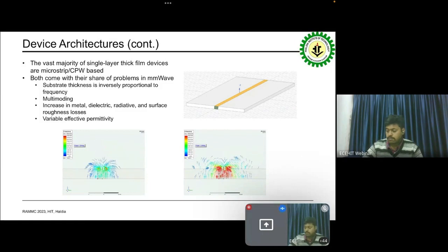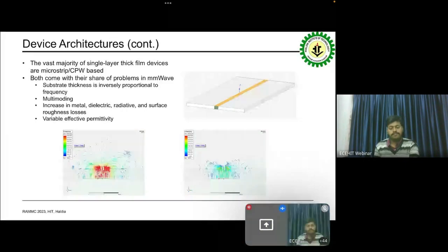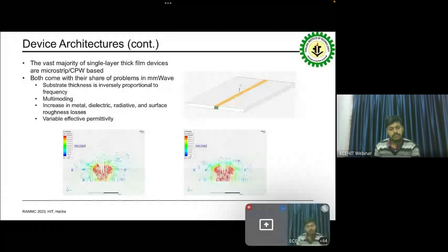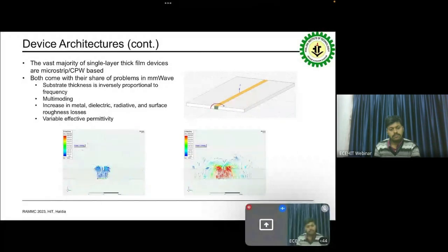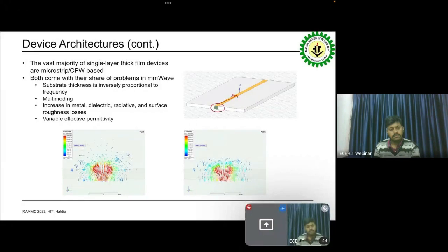At those frequencies, it might be 49.8 ohms versus 50.0. There's not enough of a difference for it to be concerning. But if you look at this image over here on the left, this is a simulation looking down this portion of the microstrip. So we're looking this way, and we're looking at the electric field pattern of that microstrip in operation.